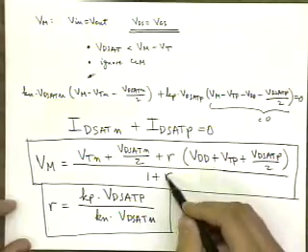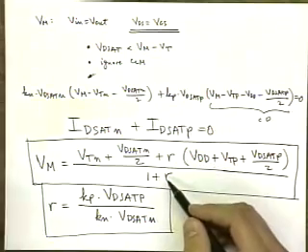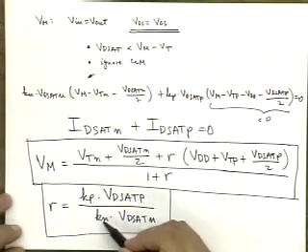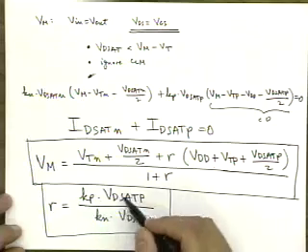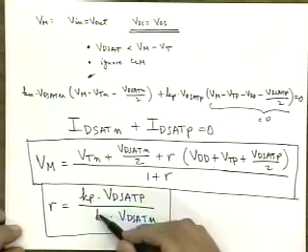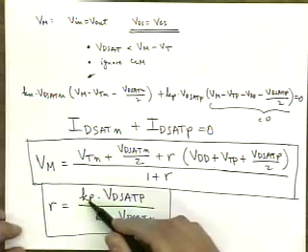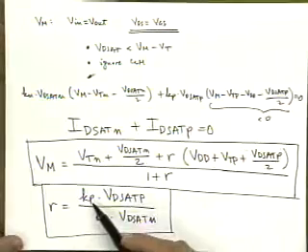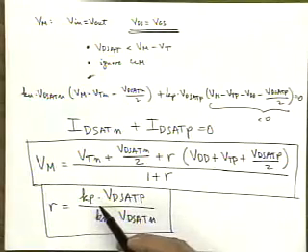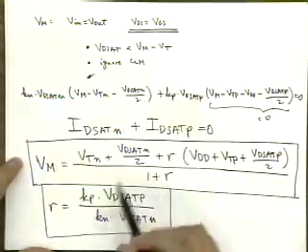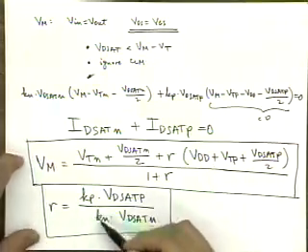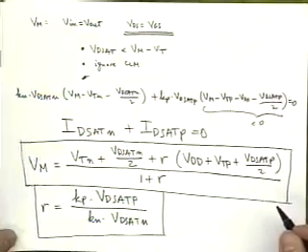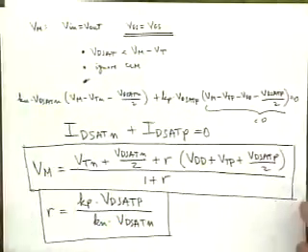So this parameter r is what can shift your threshold left and right, and that depends on the ratio of the conductivities in these two devices, where your K parameter is determined by the ratio of Kp and Kn.